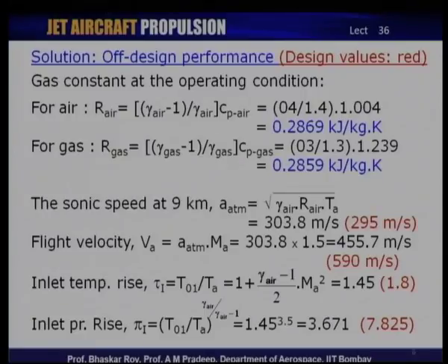Correspondingly, the inlet pressure rise, which is the conversion of the kinetic energy to pressure, that is ram pressurization, as we have called it in this lecture series. Now, this inlet temperature ratio comes out to be 1.45 using the normal isentropic relation of conversion of kinetic head to static head. The corresponding design value was 1.8. So, at 12 kilometer at design point, the temperature rise compared to the ambient temperature was much more.